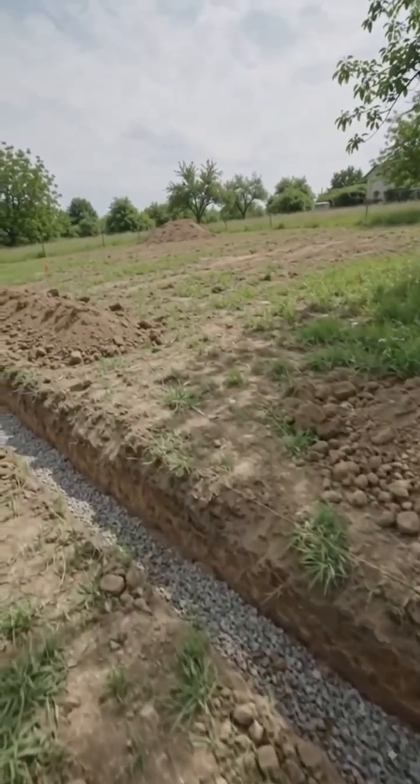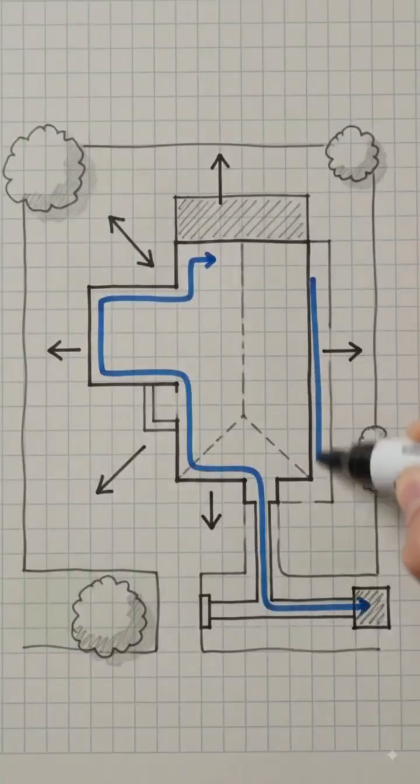Welcome to Lesson 94. Avoid wet areas with poor drainage. Grade the ground to divert water. Next, we will cover foundation tips. See you then. Lesson 95.